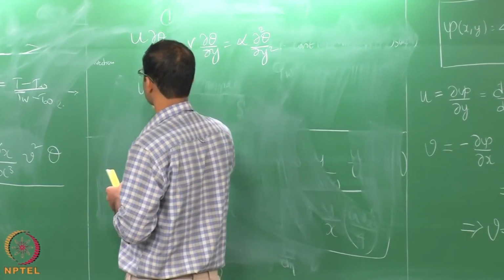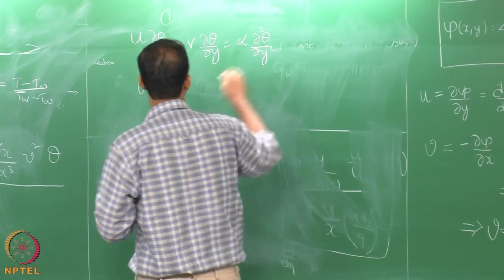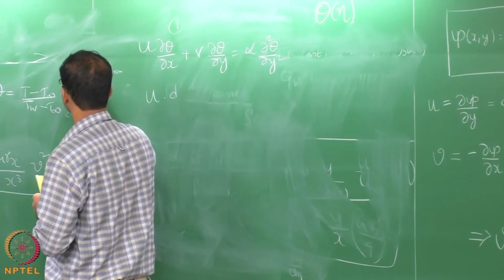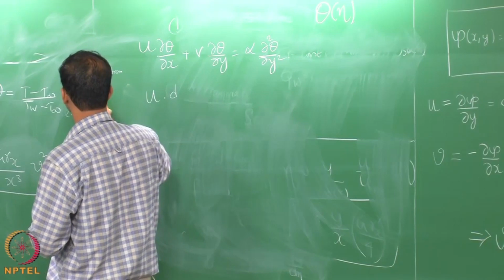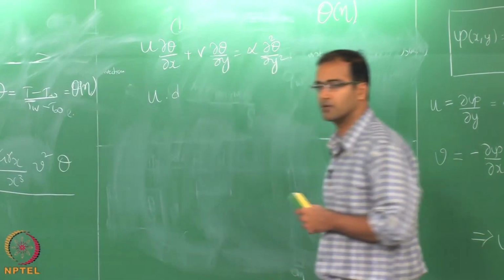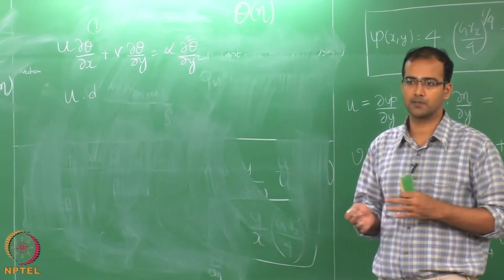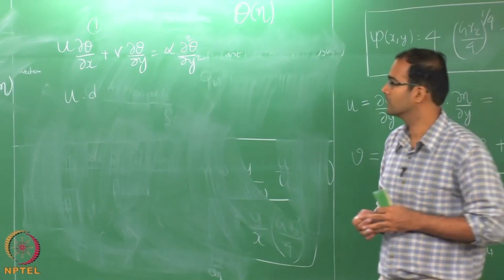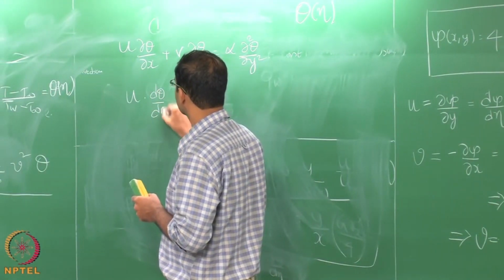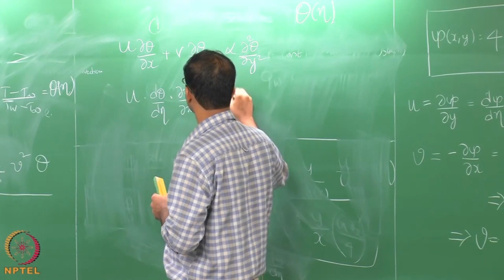So, the energy equation, we can also use the differentiation by parts here. So, you can assume now theta to be only a function of eta. Now, let us use the variable theta of eta here. Okay. So, when you plot this non-dimensional temperature also as a function of the similarity variable, they should all collapse, same way like your u by u reference. Okay. In that case, then theta will be only a function of eta. So, we can split this as d theta by d eta into d eta by dx and so on.